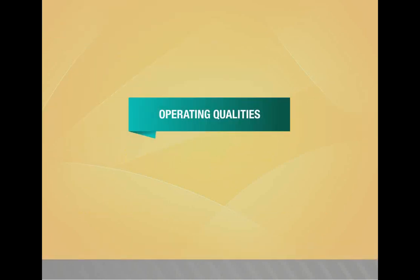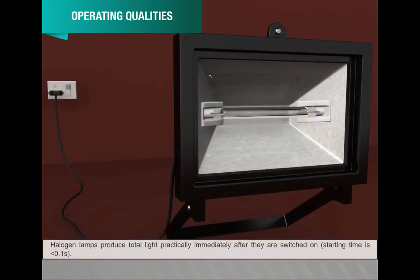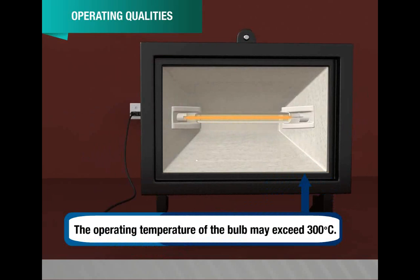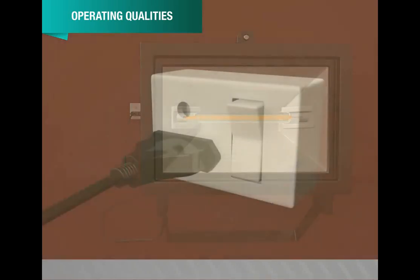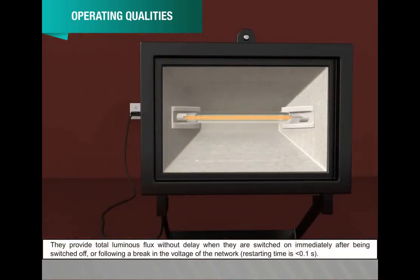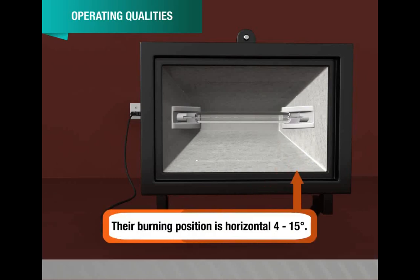Operating qualities. Halogen lamps produce total light practically immediately after they are switched on. Starting time is less than 0.1 second. The operating temperature of the bulb may exceed 300 degrees Celsius. They provide total luminous flux without delay when they are switched on immediately after being switched off or following a break in the voltage of the network. Restarting time is less than 0.1 second. Their burning position is horizontal, 4 to 15 degrees.